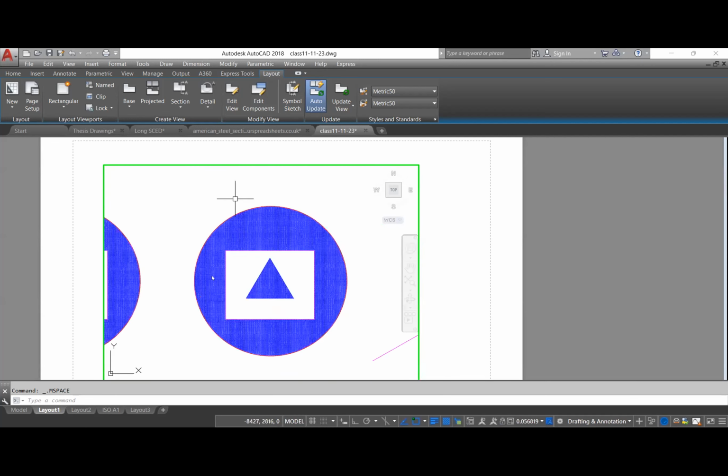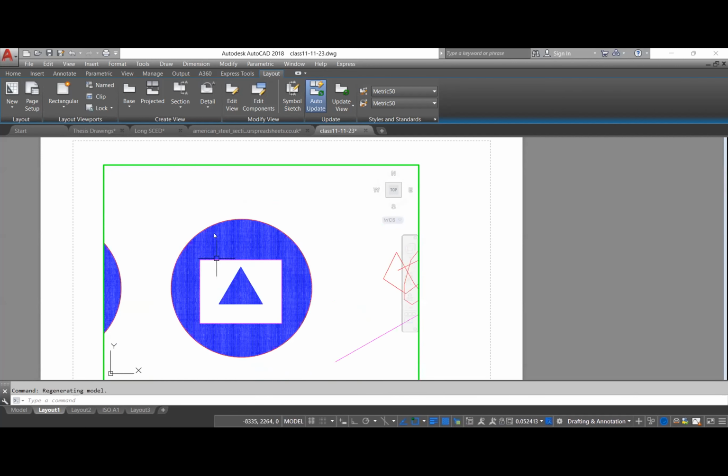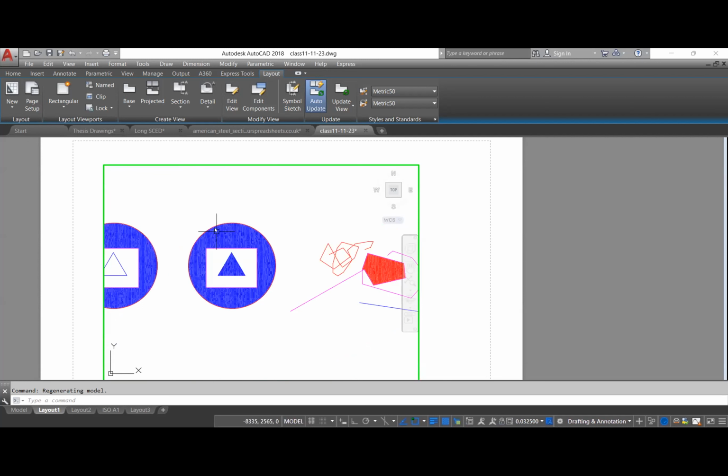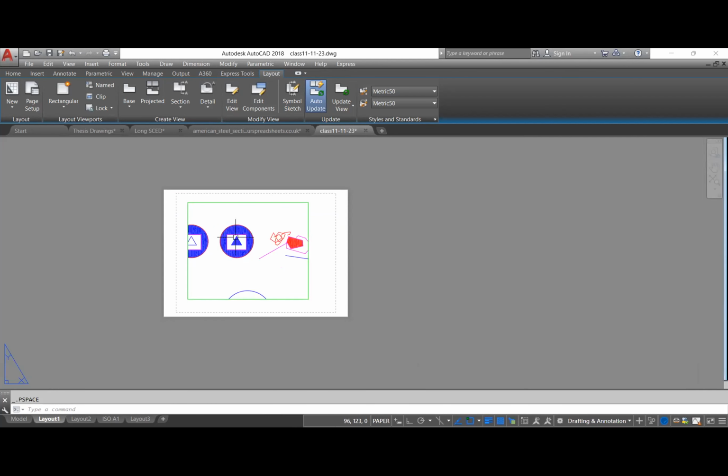As you are zooming in and out, you're actually applying a scale to your drawings. Okay, you're applying some form of scale to the drawings. So if you want to exit that floating model space, you can just come in here and click on paper, for it to change to paper. And once it changes to paper, the drawings do not zoom in and out. Now the paper is what is zooming in and out, which is fine, right? It doesn't affect anything that we are doing.